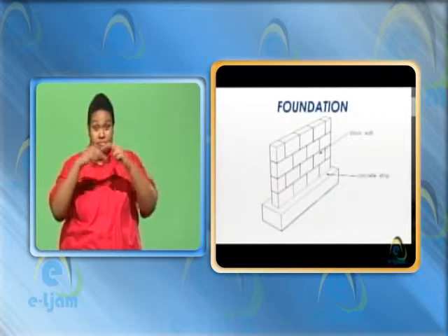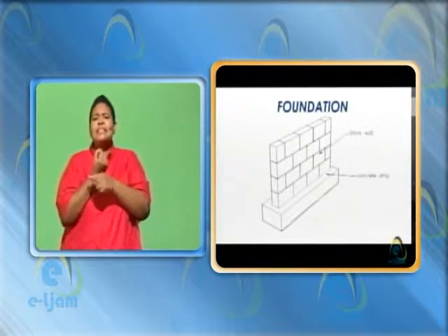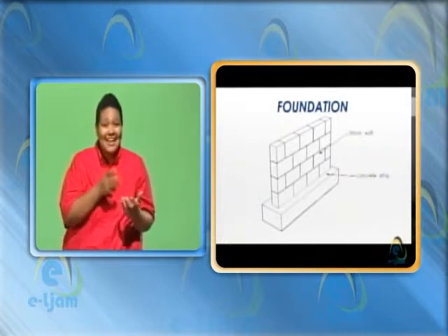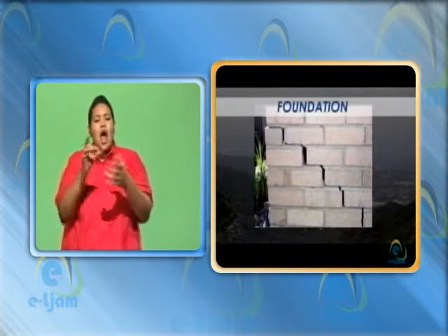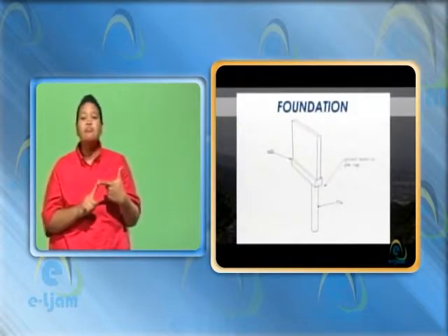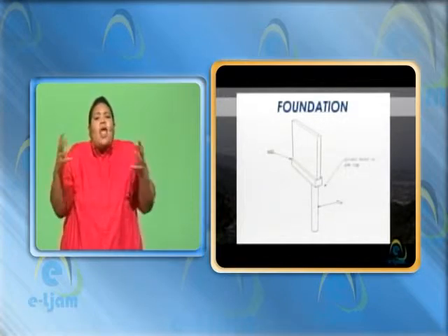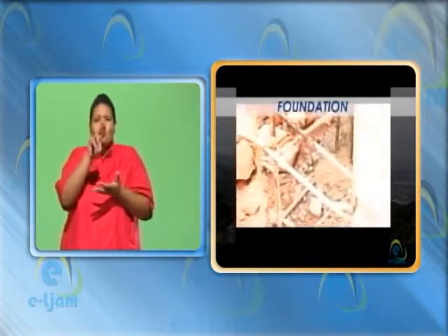Building regulation requires that the foundation of a building shall: 1. Safely sustain and transmit to the ground the combined dead and imposed load so as not to cause any settlement or other movement in any part of the building or any adjoining building or work. 2. It should be deep enough to safeguard the building against damage by swelling, shrinkage, or freezing of the subsoil. 3. It should be capable of adequately resisting attack by sulfate or other corrosive matter present in the subsoil.